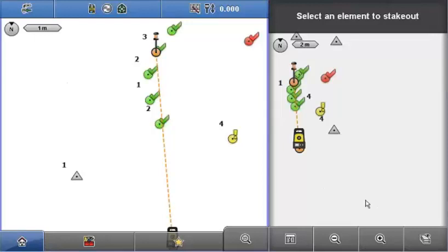Okay. So in terms of using the known point, you can use existing data you've already got, or you can measure something on the fly, as it were. Of course, you can use control, or you can maybe use the corner of a building or a large tree. For GPS it might be particularly useful, because if you don't have a station reference anyway, then you can use a local reference instead.